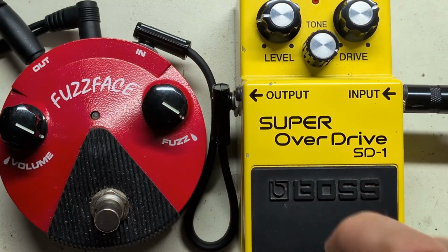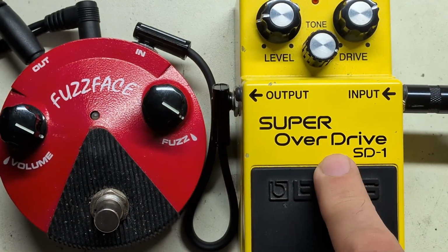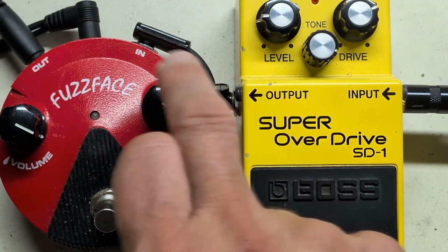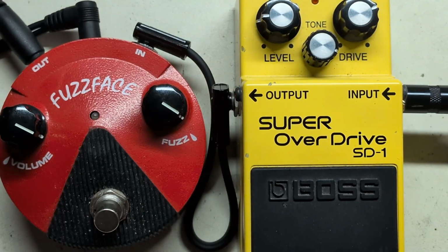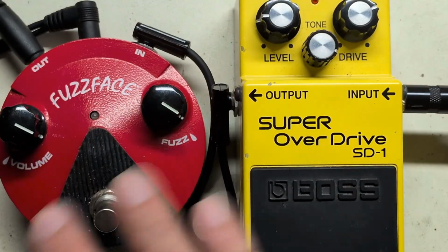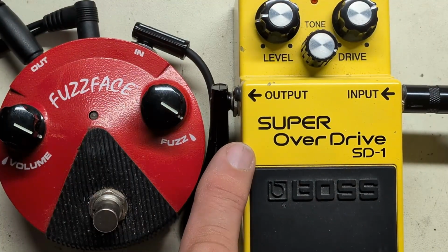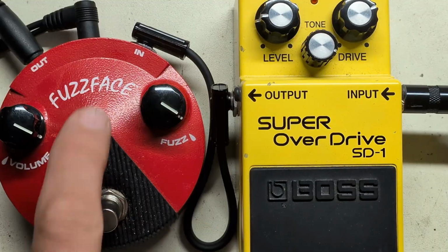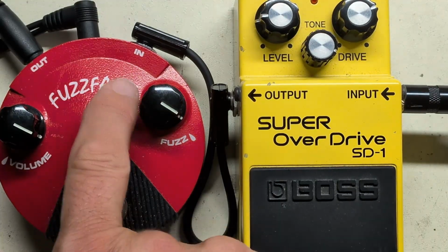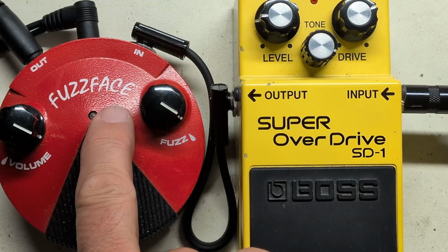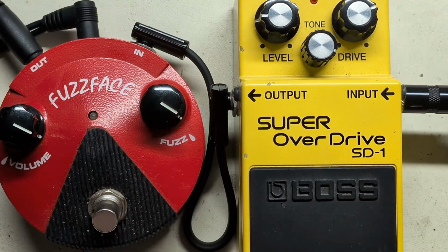Even without engaging the pedal, that's because all bus pedals have a buffer. And it's the buffer and the impedance mismatch of the output of this and the input of this that are causing that splutter, not allowing us to gain stack. So what we're going to do is look at what we can put in between here, the output of this pedal and the input of this pedal, so we can gain stack and present to the Fuzz Face a signal that it likes and that is expecting,